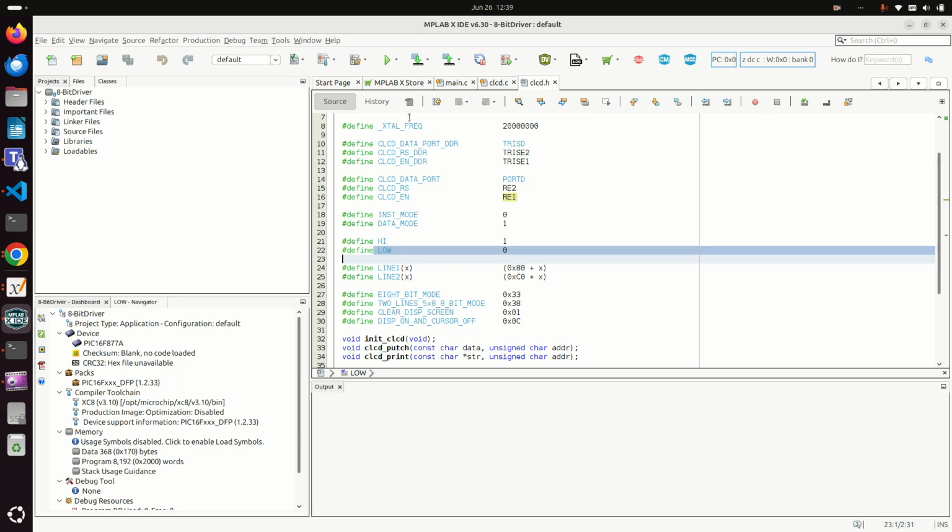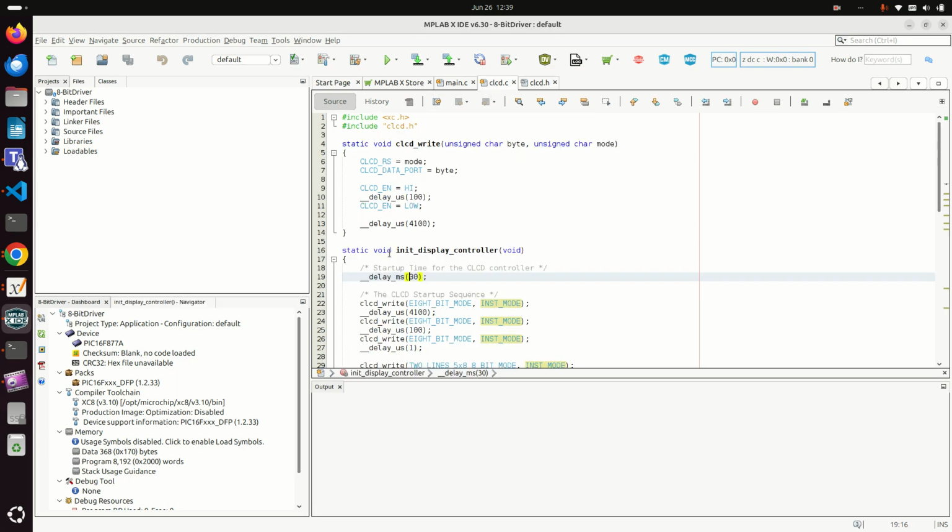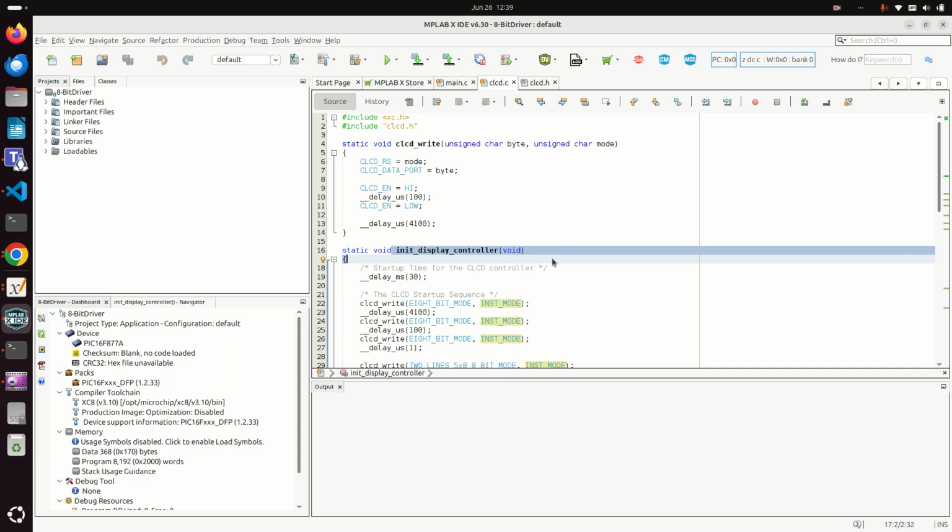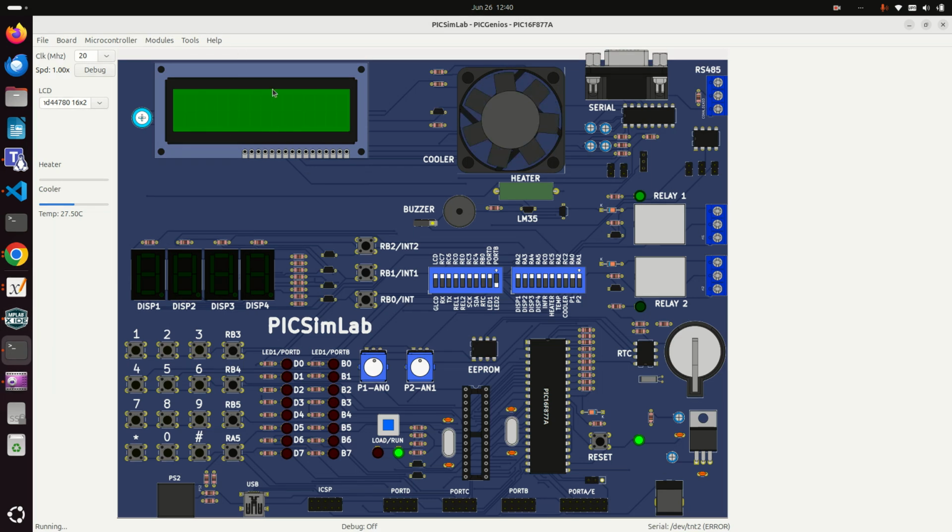So in the code we use an init display controller. So we need to use the data sheet for the initialization, right? In the PIC we use the PIC16F877A data sheet. But for this CLCD, which data sheet do we need to use? Same data sheet? No, right? Because CLCD has its own microcontroller. So what is the series number of this microcontroller?